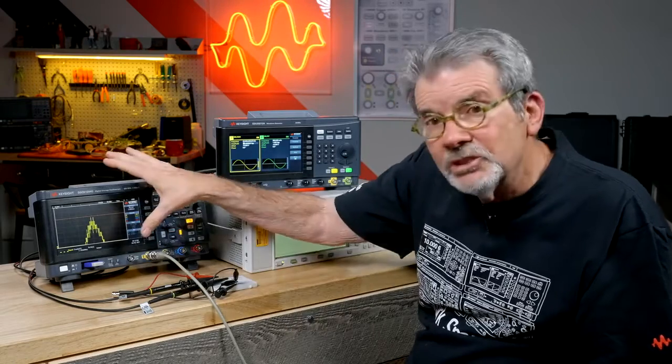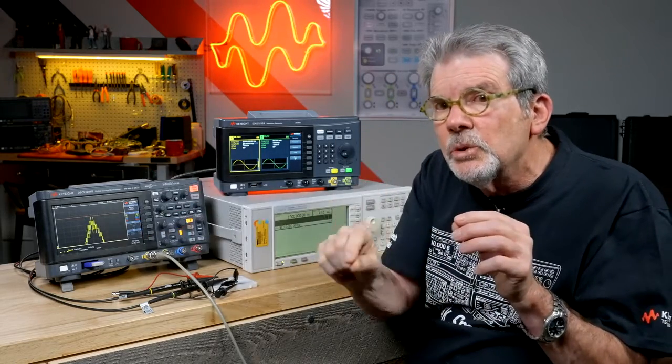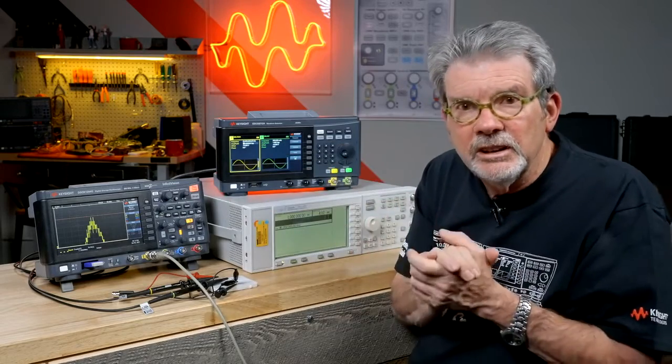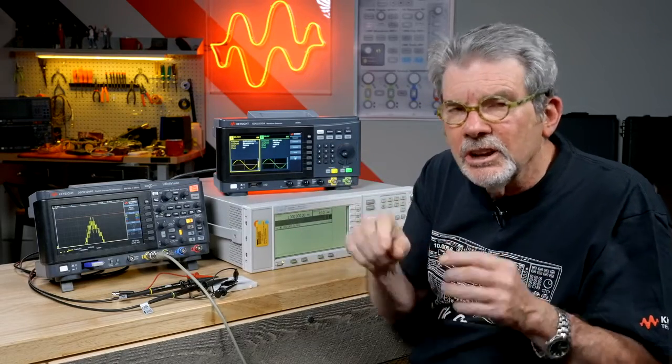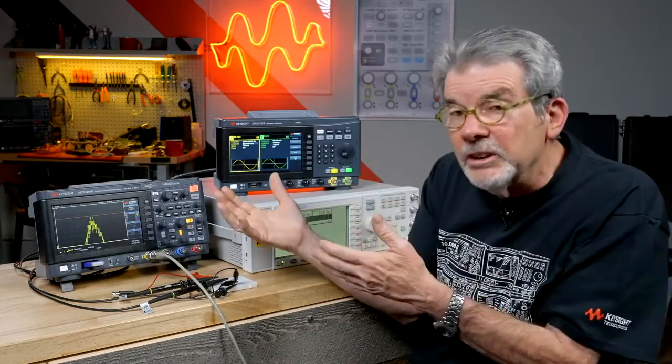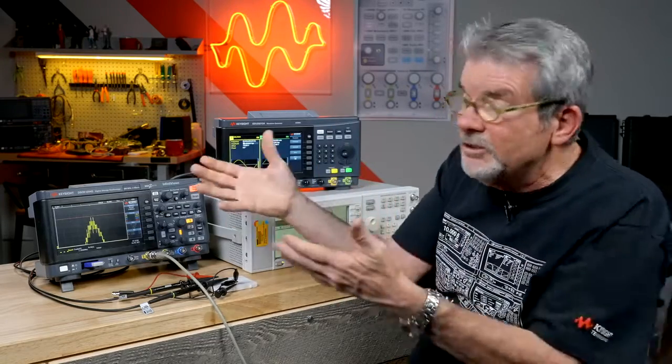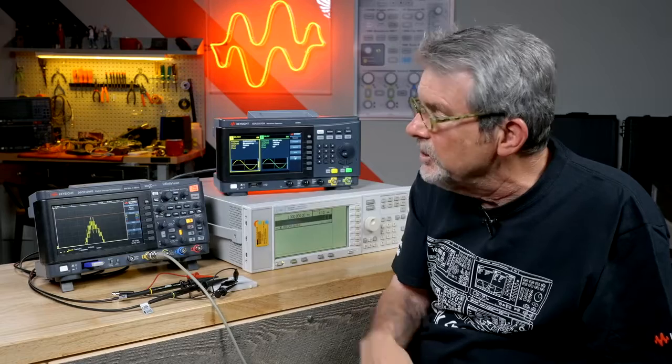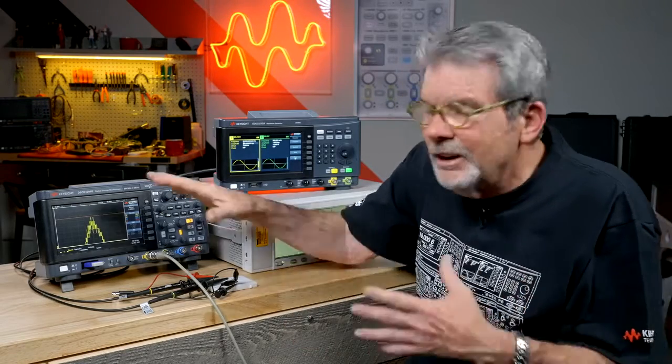Not really. Scopes have a small amount of noise inherent in them. We call it baseline noise, and that's typically more than 8 bits. And so getting more than 8 bits, especially in the university environment, all you're going to be doing is digitizing noise with more detail and not digitizing your signal. So 8 or 9 bits isn't going to do much better for this application in the university environment.